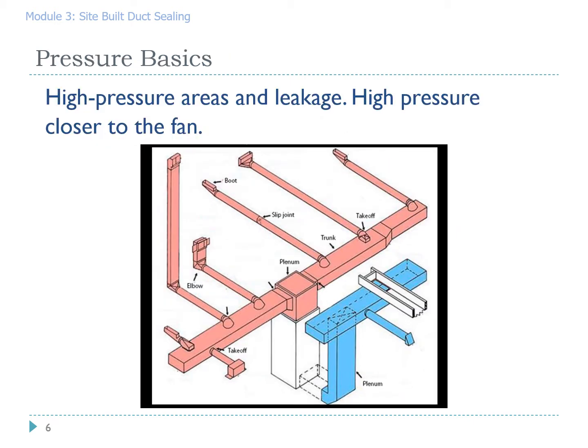The nearer you are to the fan, the higher the pressure. On the supply side, not only is the pressure higher, but the temperature is higher in winter and cooler in the air conditioning season. It is really important to fix all the holes with great care the closer you are to the fan. If you had a silver dollar size hole way out at this boot here and a silver dollar size hole at the plenum, under normal operating conditions, the silver dollar sized hole at the plenum will leak a lot more air than the silver dollar size way out here at the boot. Needless to say, you still have to seal both holes.